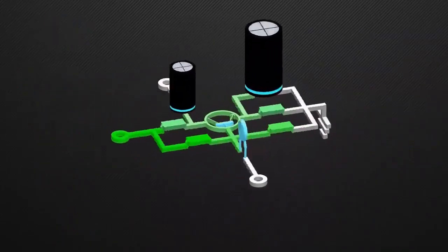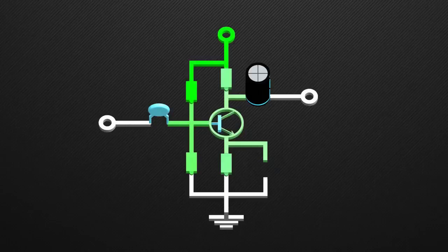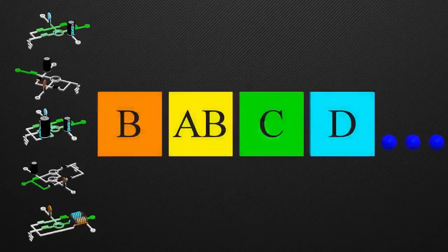This circuit has a capacitor across this resistor. This increases the AC gain of the amplifier. The capacitor will block the DC. Thus the amplification of DC will depend on the resistors, but for AC, the capacitor will act as a short circuit. Its gain will depend on the beta of the transistor, which is in hundreds. Thus you can amplify a very weak signal to strong signal.